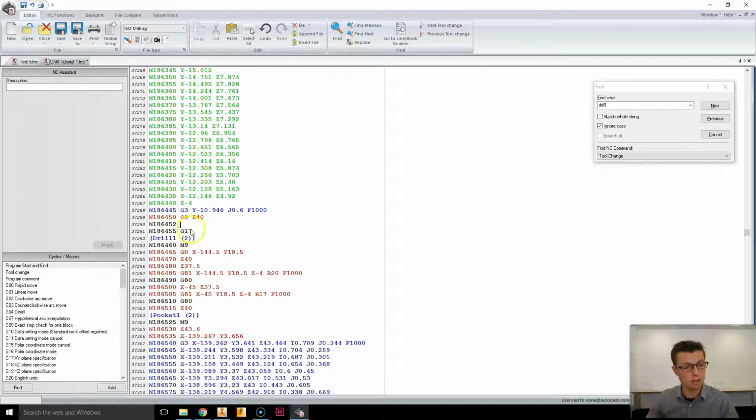So we're going to click enter. And then we're going to use the macros here. And if you scroll down, these are all the G codes, and you can click on them and find out the information of what they do. But we want to do a machine 0 return to primary reference point. So that's the machine's home, not the program home, obviously. So we double click on that, and it enters the G28 for us.